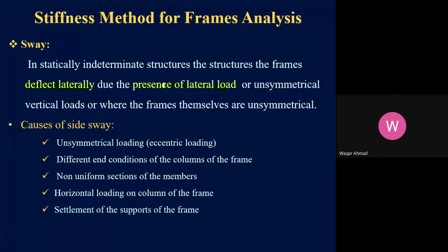In other words, the presence of lateral load is one of the reasons for lateral deflection of the frames. Or if there is some unsymmetrical vertical load on the frame members, it can also cause lateral deflection. Or if the frames themselves are unsymmetrical. So these three are the primary reasons for the lateral deflection of the frames.